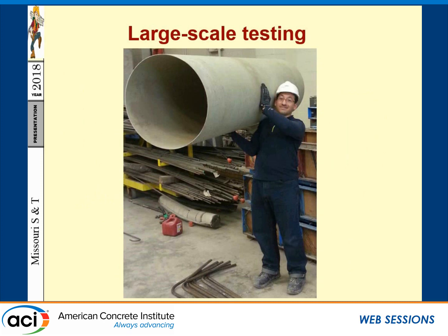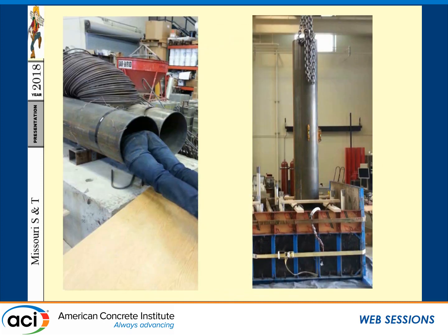And this is the FRP pipe. Here we have a bunch of strain gauges inside the steel tube. Each steel tube has about 75 strain gauges. And then when it comes to construction, we use two different scenarios. The first one relies on cast in place, using the FRP and the steel as stay-in-place formwork. So when you do your footing over here, we embedded the steel, you pour the footing, and then we have the FRP after this, and then pour the concrete between the two pipes.